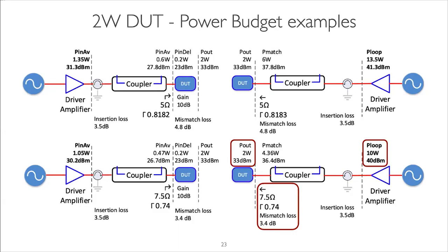You're going to have a very elaborate tuning algorithm to be able to compensate, because as the feedback amplifier is nonlinear, you try to set a certain power, but it's actually not going there because it's being compressed. So you need to overdrive it, and ultimately that's going to be a problem.